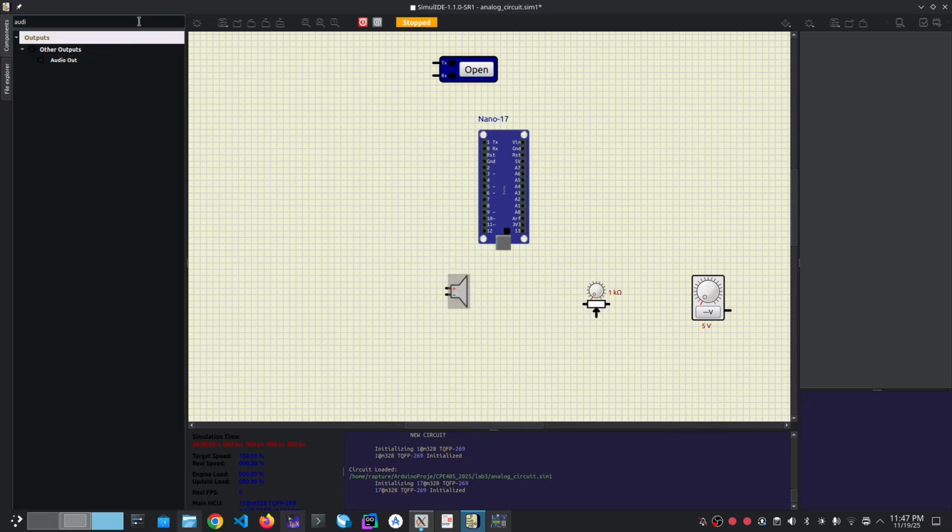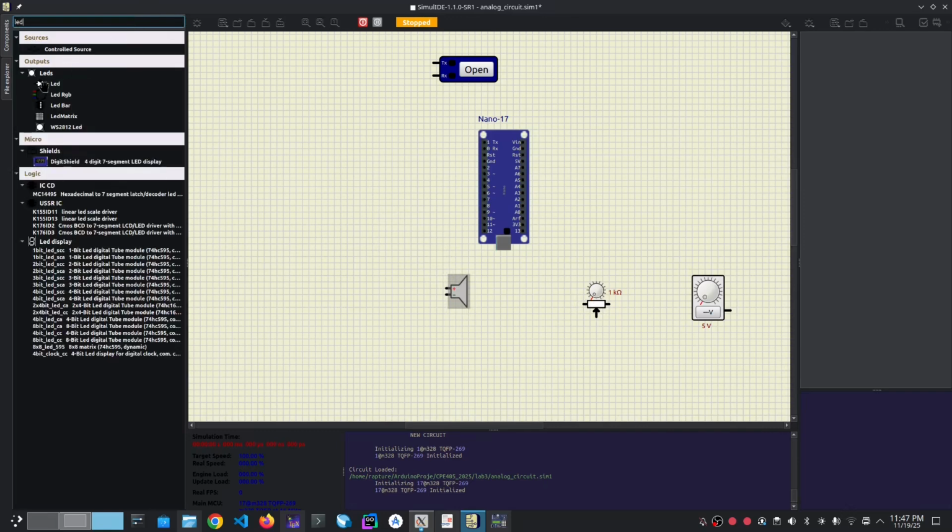Then it's time for us to connect our LED. Then we have our LED this way. You can press Control R to rotate. Then you can drop some other LED. You can just use Control C, then Control Z, so Control R. Then you can also drop one here, Control R, and also drop one below it. You can even duplicate it: Control C and Control V. Then we move it beside it.